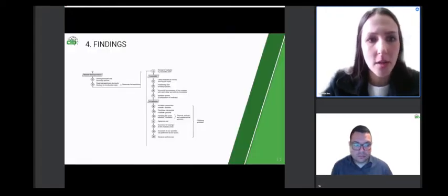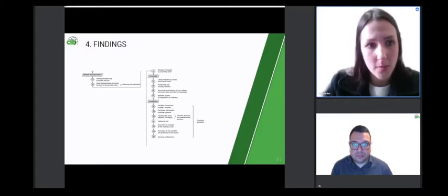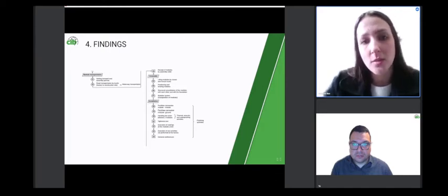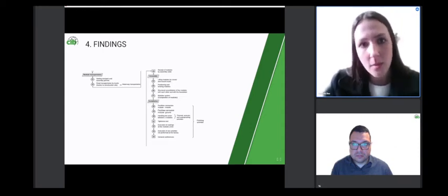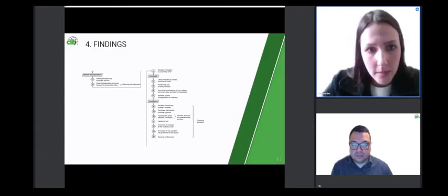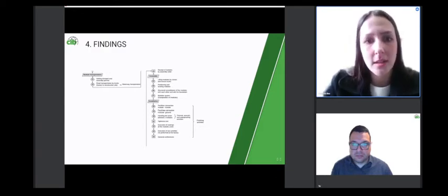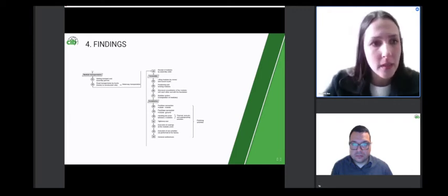Almost completed models are commonly transported by roads, trucks, and sometimes by waterways, ships, to the construction site. This stage ends with the receipt of the models. The assembly stage begins after receiving the models at the construction site. The lifting activity is usually performed by cranes or boom trucks. Upon lifting, the models are positioned and leveled. Once the positioning is completed, the modular units are consolidated, forming a modular system, that is, a composition of models.